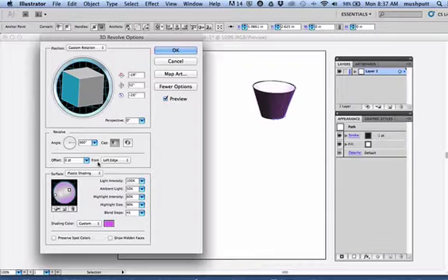The next feature is from left edge. Right now, the left side of the path that was drawn here, which is sort of a backwards L, is the direction that the revolve went. But watch what happens to the shape if we have it revolved to the right of that path. So this path, if it's revolved right, becomes a cone. If it's revolved left, we get a bucket. Keep that in mind.